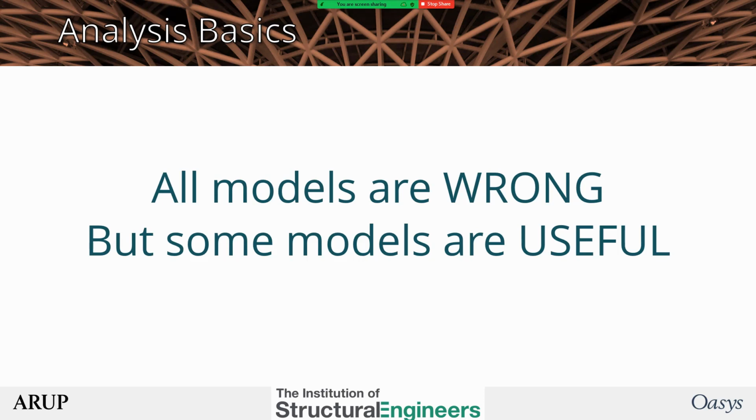Is it possible to do a totally realistic model and test it with everything the real structure will experience over its service life? No. The closest you can get is to build the structure for real out of steel and concrete, then load it until it breaks, then repeat with other loadings. But would that be 100% accurate? Well, no, that won't be either. Due to tolerances, the steel and concrete sections will be slightly different sizes. The frame won't be quite as plumb. The wind, snow, and earthquake loads will not be exactly the same. Besides which, we don't know exactly what the structure will experience over the next 50 years. It's just not possible. As I said, the art of engineering is to get answers which are close enough.